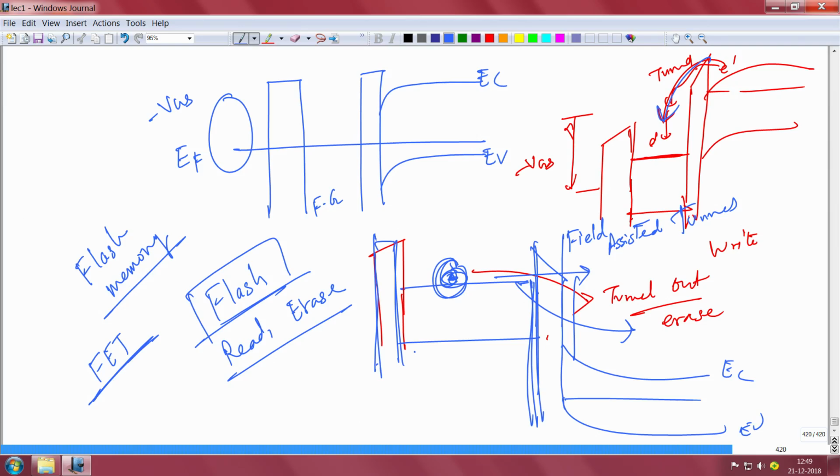But this is a main application of semiconductor memory, the flash memory, which uses a floating gate and a tunnel oxide to essentially tunnel the electron in and out to read and write the data. This is unique in application. You cannot do it in non semiconductor based devices very well. So this is a broad application of a transistor as a memory device. What remains now is the transistor as high speed logic. I have already discussed the transistors that are useful for high speed logic, which is silicon MOSFET. That we will discuss in the next class perhaps.